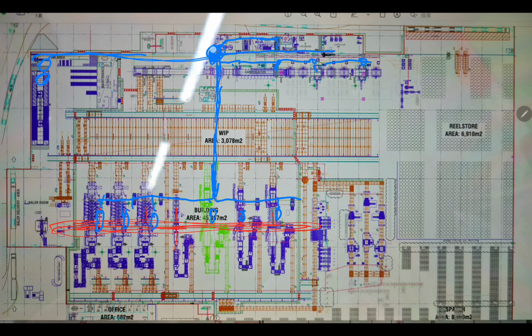So this is the manhole, and underground is the master tank. An agitator is installed, and it comes to this treatment line. The water treatment line separates the glue, ink and the crystal water. This water is not suitable to use in the boiler, or you can use it in the glue kitchen. It is only used for agriculture and for flush water. Do not use it for drinking, do not use it for glue, and do not use it for the boiler.